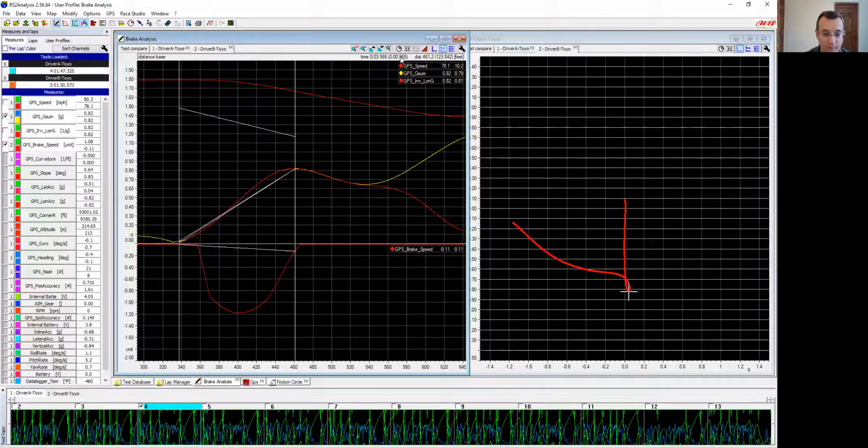And also, if you have aero in your car, that's going to also change, because that's going to change the normal force at the tire, which is what friction acts on. So the more weight on your tire for a given level of friction, that allows you to slow down at a faster rate. So those are why things like the aero on the car can make a big difference in terms of the amount of braking that you can do, and you actually have to ease off on the braking on an aero car as you get deeper in, because the normal load on the tire is reduced as your speed is reducing. Perfect. Hopefully that helps you make sense of why you won't always see the same number.